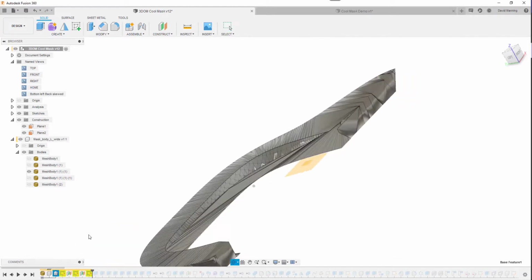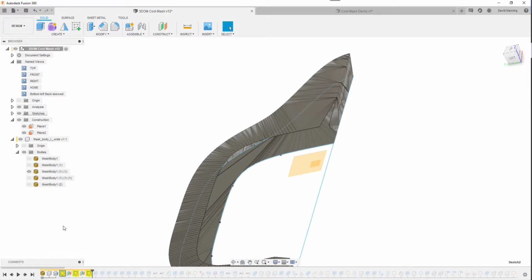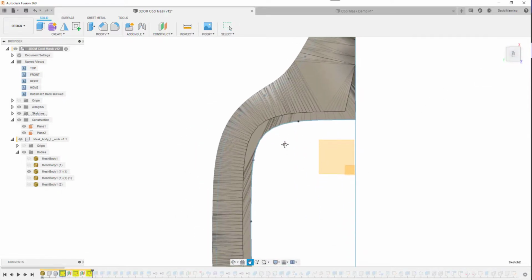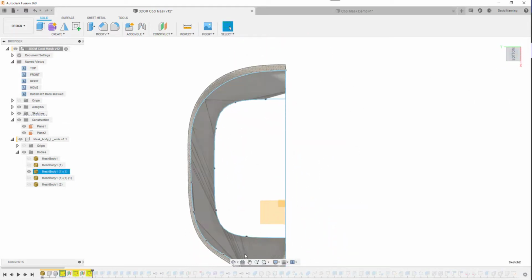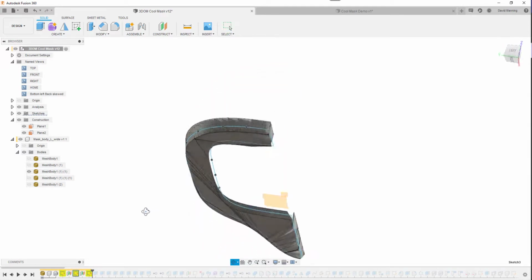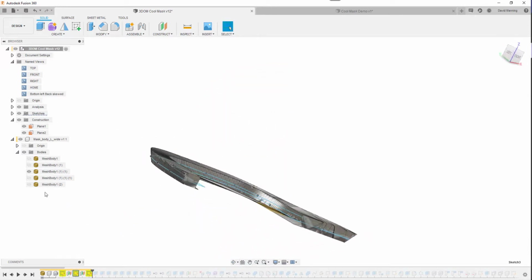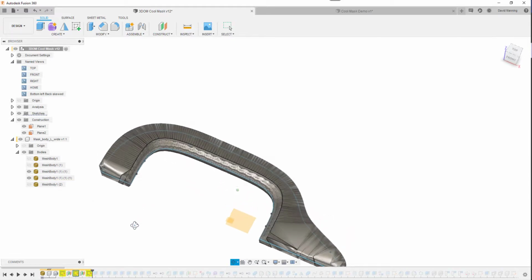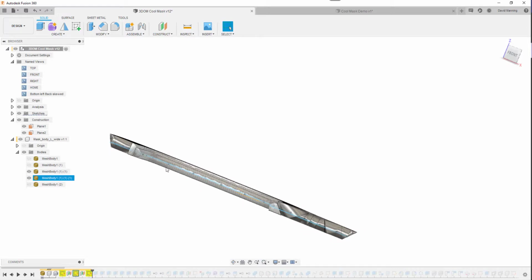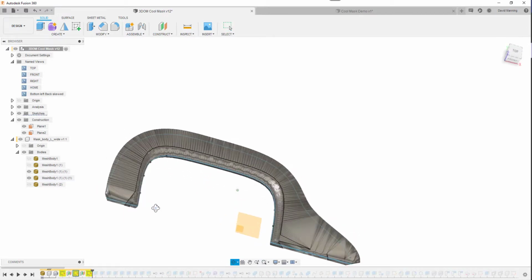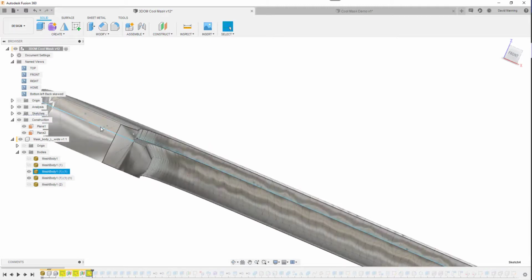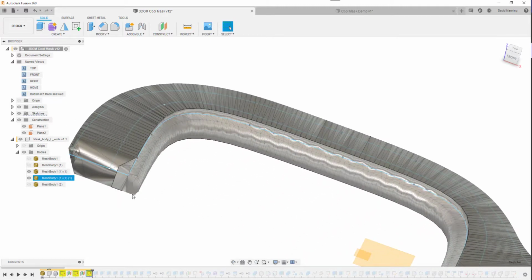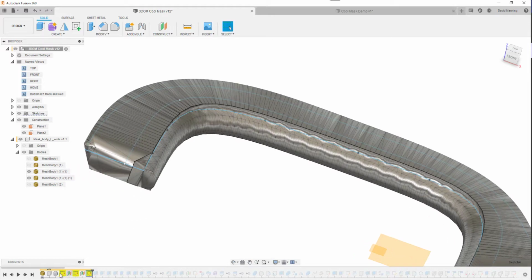What I have done is built out some sketches. Now you can see there, if I go to top view, it's a bit more clear. I have projected, or rather bottom view, that plane there, and then I did a plane that sat through the edge. Let's turn on the next mesh through the middle of that bulge there, because I want to change this into a solid and just be something a bit more useful to me. And then the last thing I did was the top of that shape there as well, because that's the last one I'm concerned with, because that is the interface where it's going to snap into.